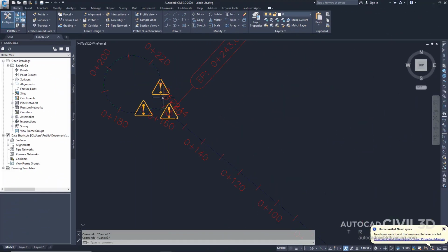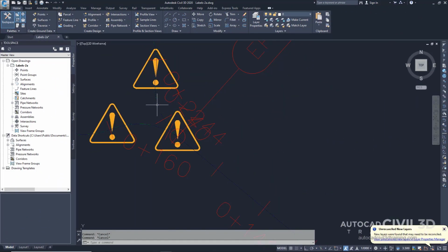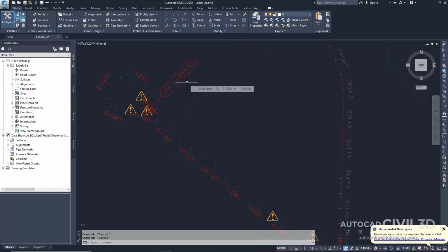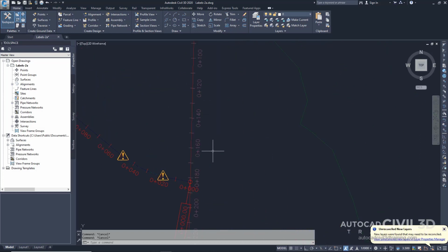When the alignment is created, it's created in green. The green color is controlled by the alignment style that you specified in Step 3. Notice that the new red labels are brighter than the labels that were brought in with the externally referenced objects. The color tones are different so that you can easily identify where the labels reside.